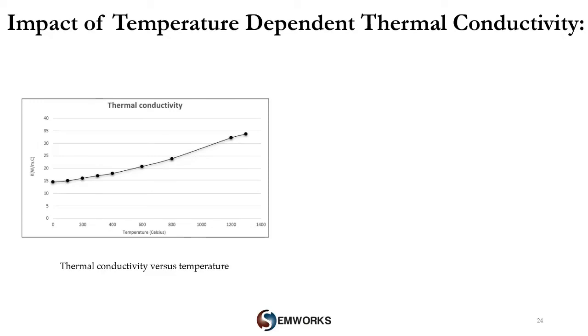So, to get as close as possible to the concrete hardening conditions and to accurately predict the achieved temperature magnitude and profile, EMS allows to use nonlinear temperature-dependent material properties for electromagnetic, thermal and mechanical properties, with an internal two-way solving between the electromagnetic and thermal solver within the same analysis and inside the same interface.